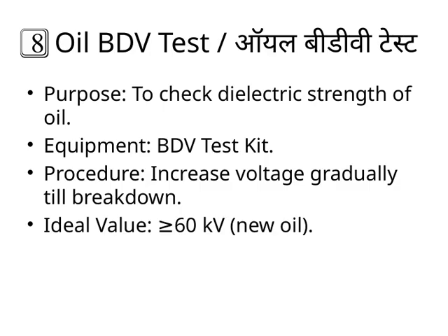To perform this test, we use a BDV test kit, which is specifically designed for this purpose. The procedure involves gradually increasing the voltage applied to the oil sample until it breaks down. This step-by-step increase helps us determine the point at which the oil can no longer withstand the electrical stress.